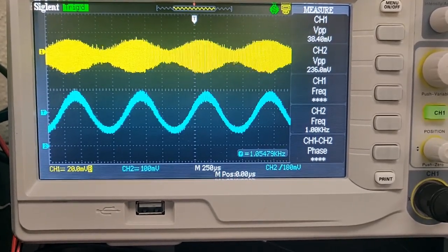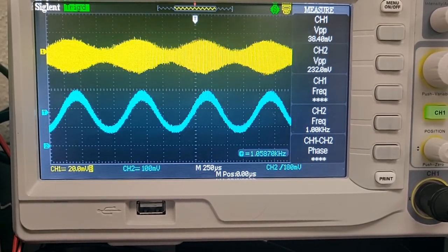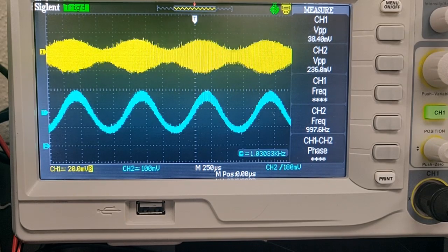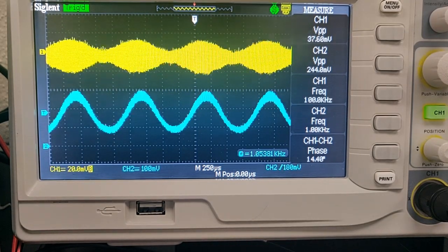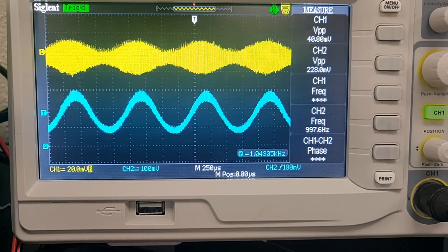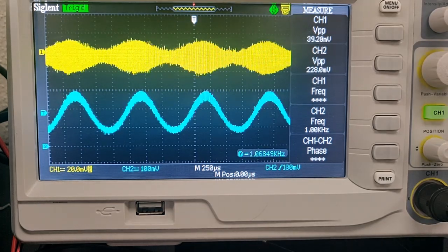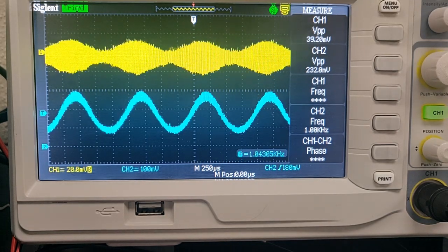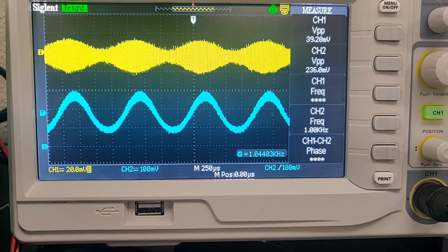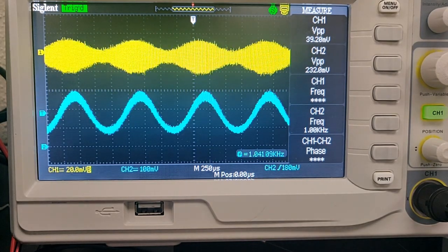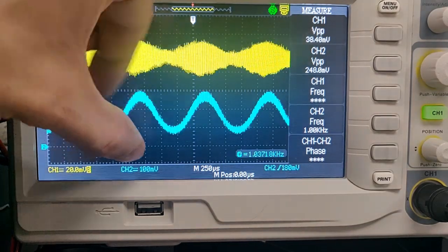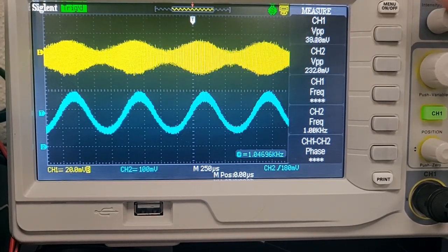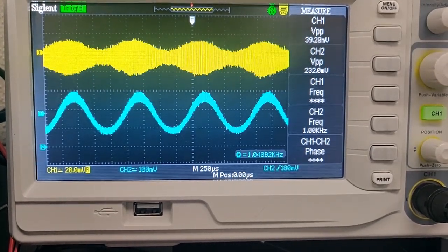All right, so I went ahead and added the components from figure 9 so that we can fully demodulate our carrier wave. You can see from the figure that we added a couple of capacitors, a resistor, and a diode. The capacitor and the resistor form another low-pass filter so that we can remove the high frequencies of the carrier wave. And the diode was just to select out the piece of the envelope that we were interested in. So, put it all together, we have a demodulated signal.